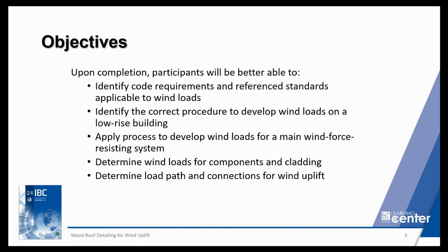We're going to identify the code requirements and reference standards that we're going to apply in our example today and the overview that we'll do. Talk about the correct procedures to develop wind loads, and we'll be using the envelope procedure today from ASCE 7.